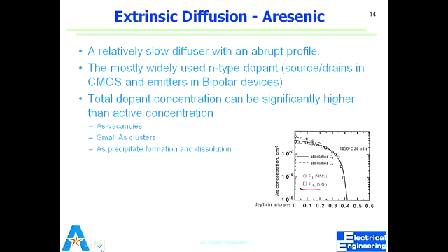So much more crowded dopants which don't necessarily contribute actively, is that good or bad? How? It's taking the space. It's degrading, it will degrade mobility. It will degrade the travel of charge carriers because it will be much more crowded. What happens in a crowd? You bump around much more. There will be many more collisions. So collisions would retard the travel of charge carriers.